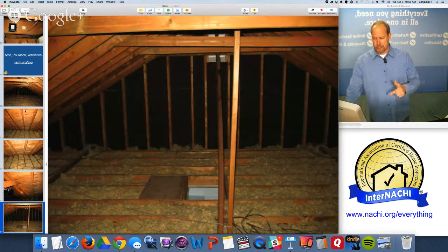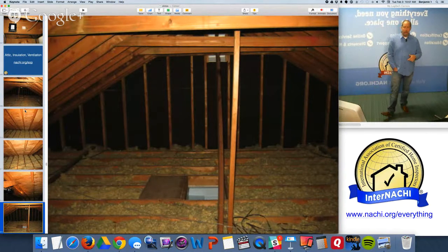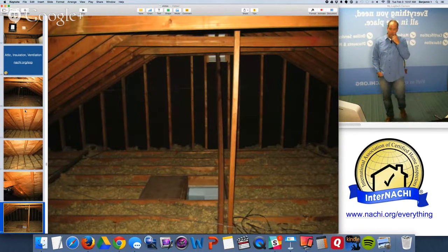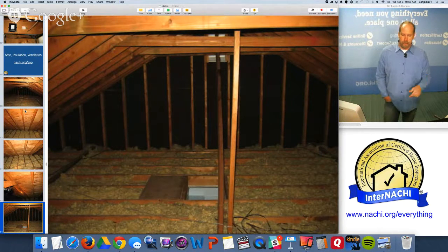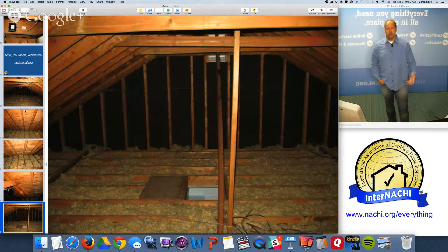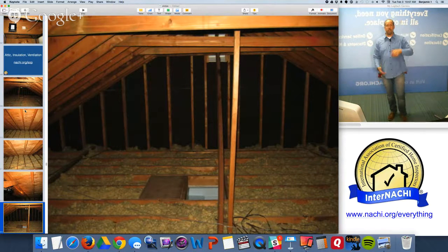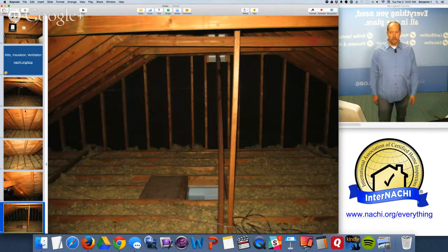The attic access, you can see, is basically a big hole allowing conditioned air to escape into the attic out of the house. It's like 100 cubic feet per minute. It's not sealed, it's not insulated. It's a huge energy loss. The heating and cooling system is already inefficient, 65% efficiency, and now you've got a big hole. So you waste a lot of energy conditioning the home, and a lot of that conditioned air is escaping outside, essentially, through an open window.